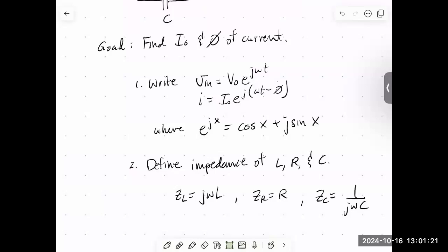And we realized that as soon as we substituted our derivatives back into the loop rule, the differential equation, we could express the voltage loop rule as: the voltage provided by the function generator was equal to current times something involving inductance, current times resistance, that's the voltage across the resistor, and current times something involving the capacitance.